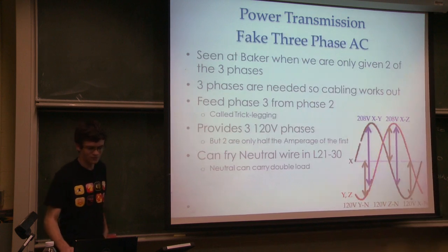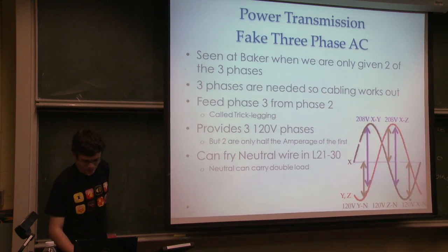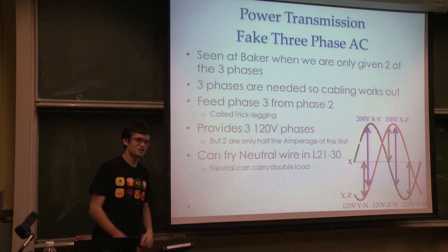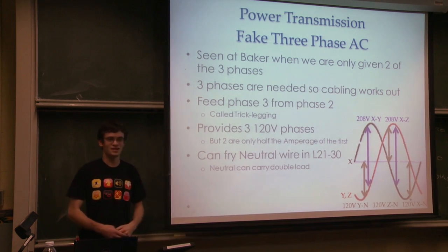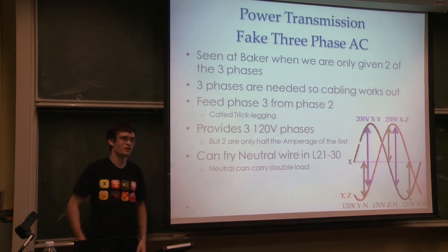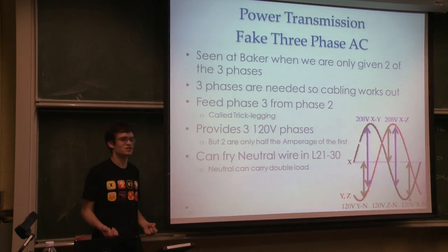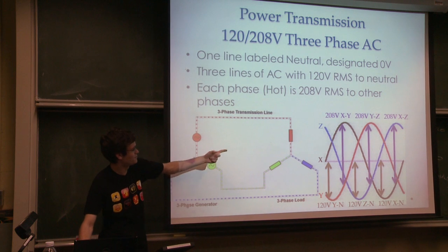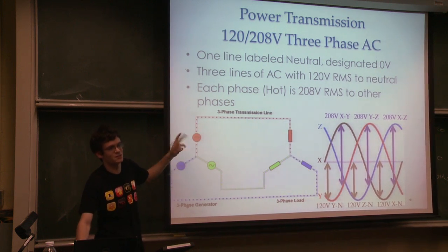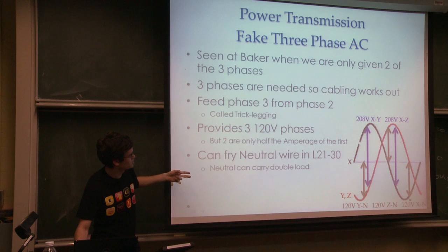Okay. So I thought I moved that around. So in some places on campus, tech needs 3-phase AC because a lot of our gear is based on having all 3 phases present and then tapping off each of them individually. You can tap each of the 3 phases individually, or you can tap them in pairs and get the 208 volts.